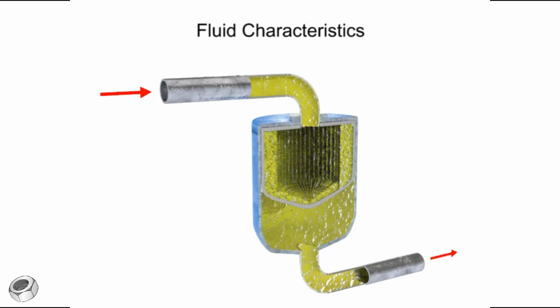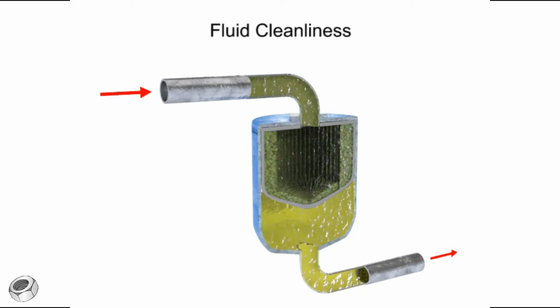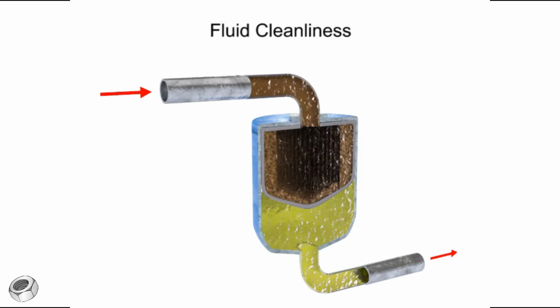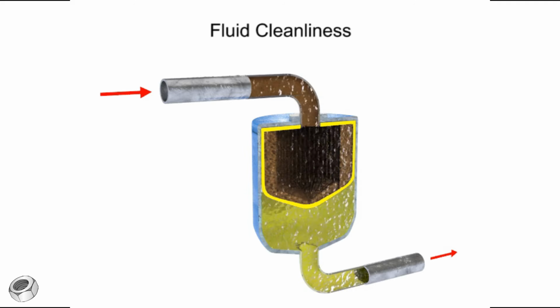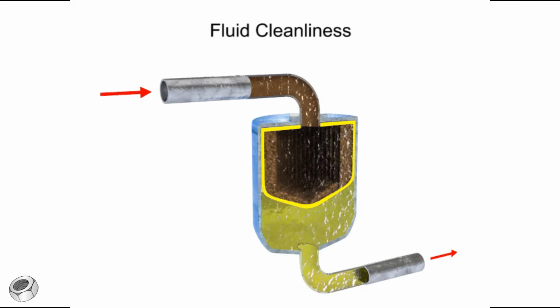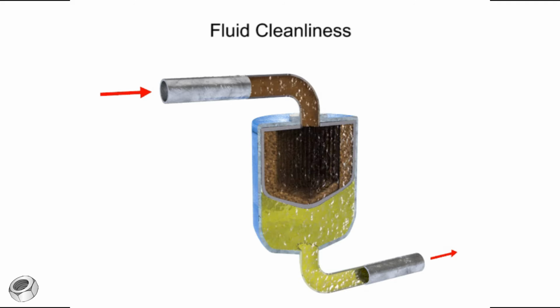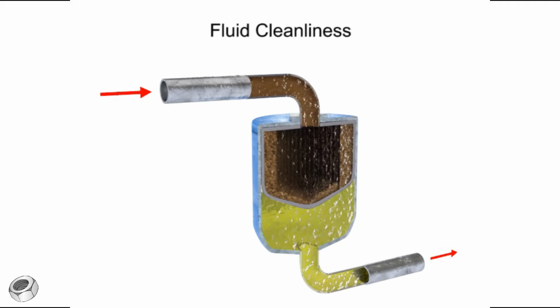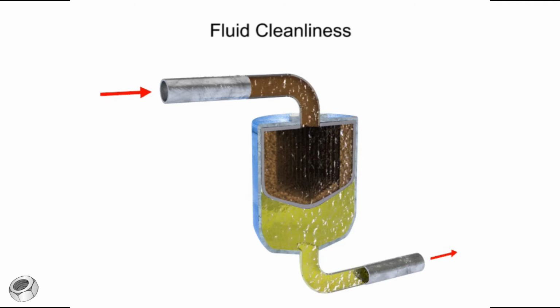Several factors should be considered when designing a fluid system that uses a petroleum-based hydraulic fluid. The first is cleanliness. Oil never wears out, but it can become so contaminated that it is unfit for further use. Fluid systems frequently employ filters throughout the system to help reduce contaminants. They may also require complete fluid replacement after certain time intervals, and this can become cost prohibitive with larger systems.